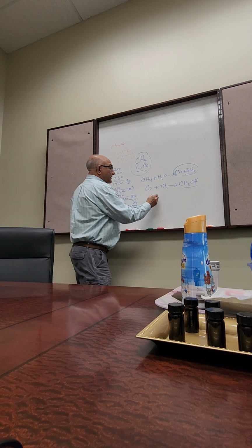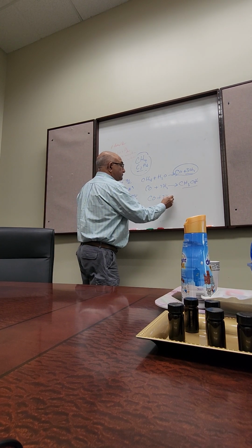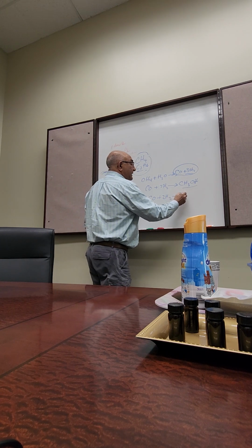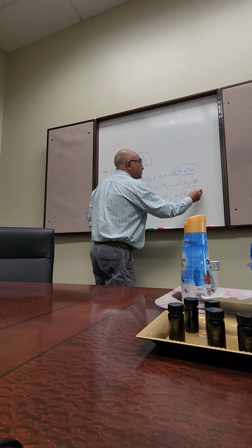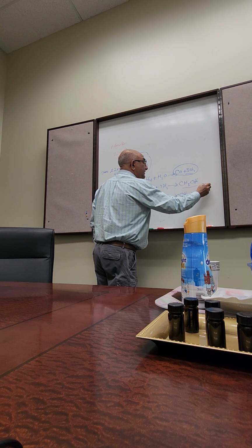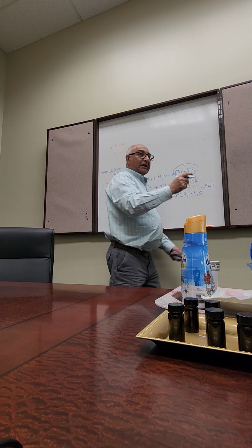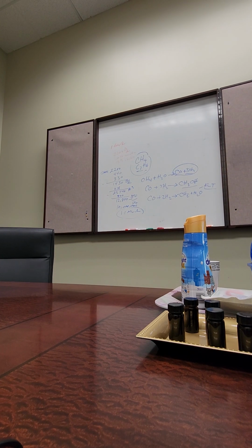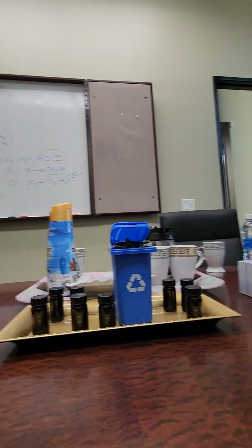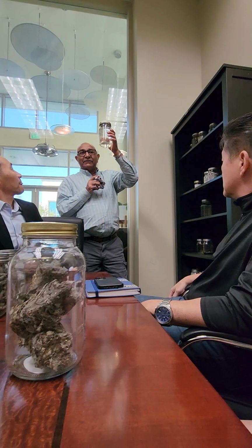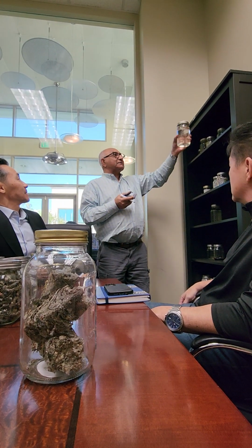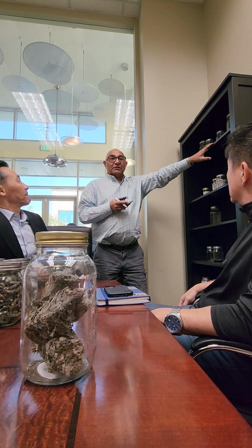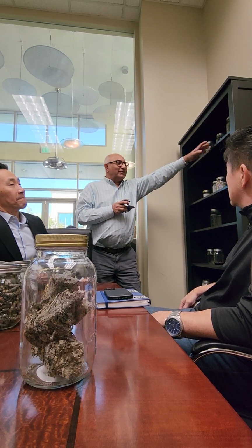And carbon monoxide and hydrogen will give me CH2 plus water, H2O. This is called Fischer-Tropsch, FT process. And we can make liquid fuel. We can make an FT liquid fuel. Right now, in the United States of America, it's about $9 a gallon. The US government subsidizes. The reason is because all of it becomes jet fuel. And jet fuel is very expensive.